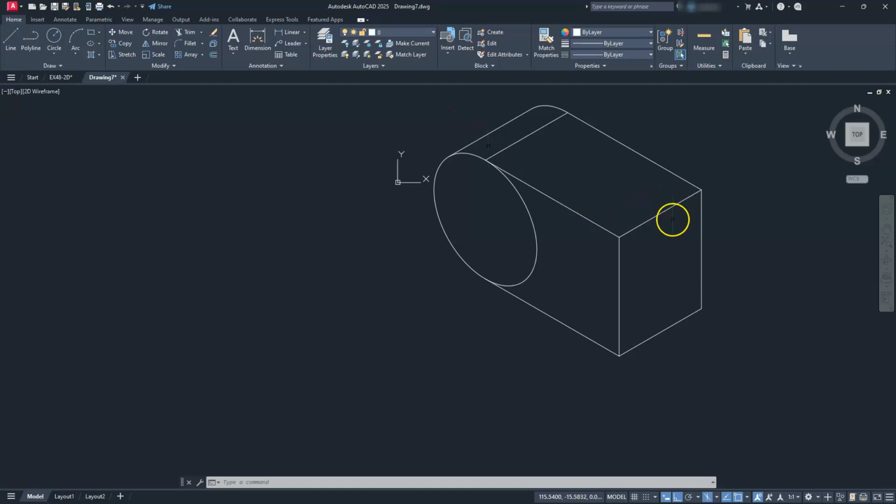So I'm just going to draw a line from this midpoint at 50. So let's start off with the line, go from this midpoint, and I'll go over a distance of 50. Let's switch to isometric top. So I'm just going to select here, go to isometric top, start with the line command. I'll just draw it going this direction here, and that height is going to be 20.